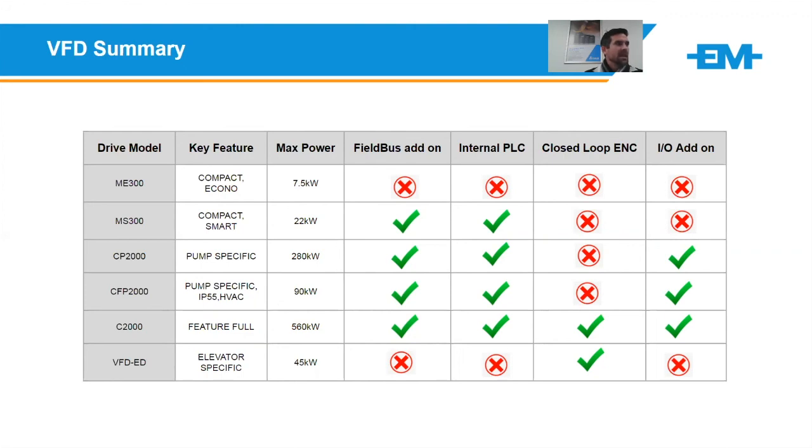There are functions in the M series drive to have one drive and two motors, and you can set up two different overload tolerances or two different motor setups and have the drive run one motor through a contactor and run the other motor through a separate contactor independently. Or you can have one drive with multiple motors running at the same time at the same speed, but you cannot run the M series drives with active outputs and paralleling those outputs up while they're active. No, it will not work. It'll trip.